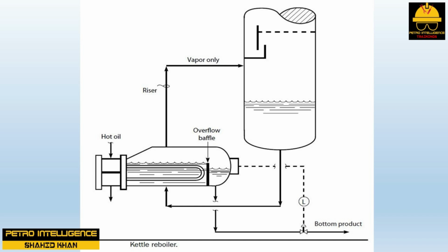This means that an increase in the reboiler heat duty results in an increase of liquid level in the bottom of the tower. Should the liquid level in the bottom of the tower rise to the reboiler vapor return nozzle, the tower will certainly flood, but the reboiler heat duty will continue. Unfortunately, reboiler shell side fouling may also lead to tray flooding. This happens because the fouling can cause a pressure drop buildup on the shell side of the reboiler.